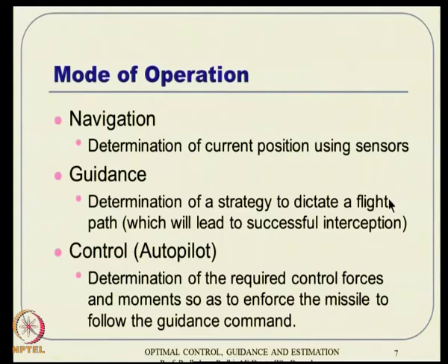Alright, modes of operation. Typically, we are not bothered too much about propulsion and structures, things like that. We are bothered about navigation, guidance and control. So, that is the primary motivation for us. The navigation is nothing but determination of the current position. All that it does is use some sensors, and that is a big task of course. Using some sensors, it finally finds out where the current location is, typically in the inertial coordinate frame actually.